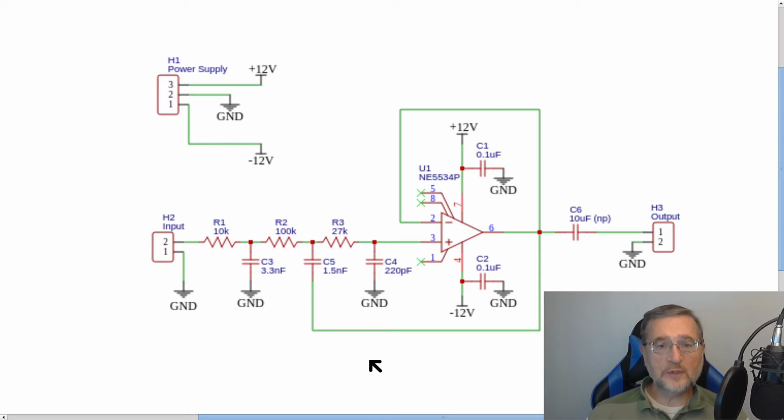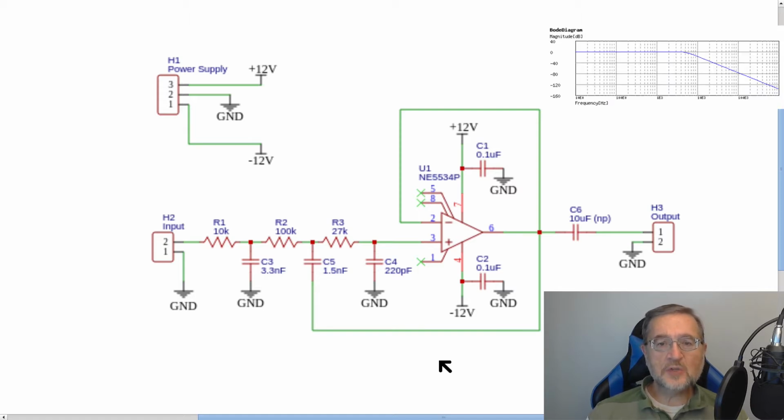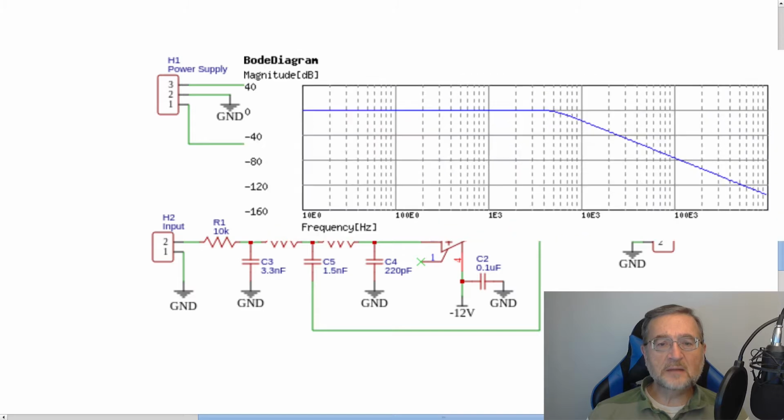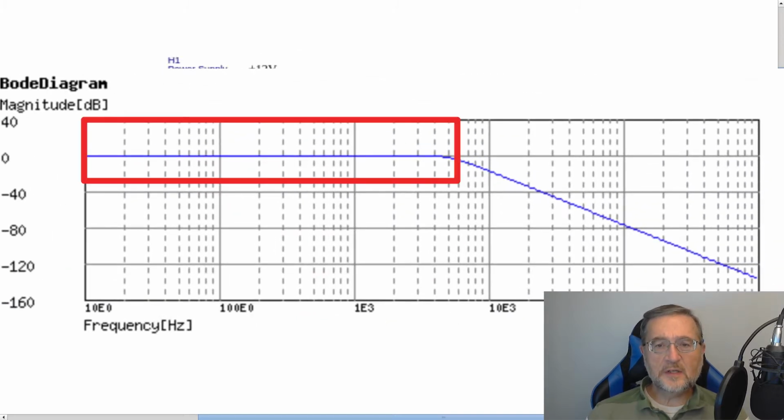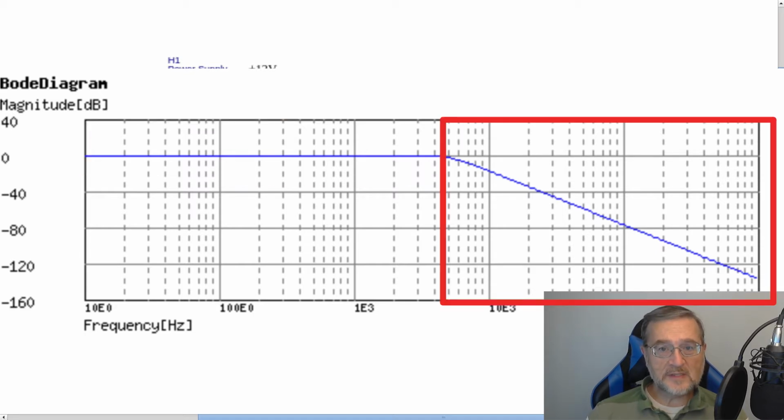Without going too much into the details, I just say that I made the calculation based on the Butterworth filter, a design that sets those parameters we just talked about in such a way as to provide the most possible flat band in the passband region, while assuring a smooth transition from the passband to the stop band. The passband region is the region of the response curve of the filter where the signal is supposed to pass through unaltered. In the stop band region instead, which is the band where the filter actually modifies the input signal, the response curve goes down fast with the increase of the frequency.